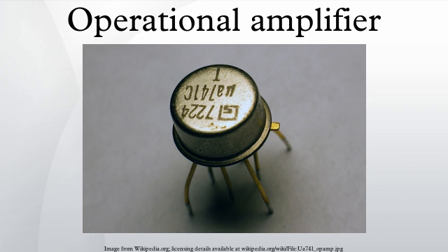Common mode gain. A perfect operational amplifier amplifies only the voltage difference between its two inputs, completely rejecting all voltages that are common to both. However, the differential input stage of an operational amplifier is never perfect, leading to the amplification of these common voltages to some degree. The standard measure of this defect is called the common mode rejection ratio. Minimization of common mode gain is usually important in non-inverting amplifiers that operate at high amplification.